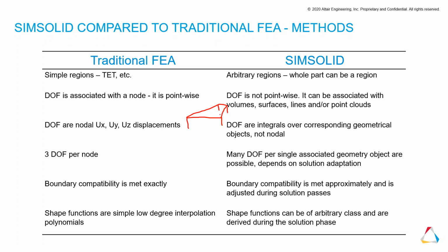We don't break this entire table into small tetra elements or hexa elements. We can break it down into, probably here, 5 elements: one element to represent each leg, and then one element to represent the table. I say element here just for you to imagine. We don't actually use elements, but imagine that we can break down into these few elements.